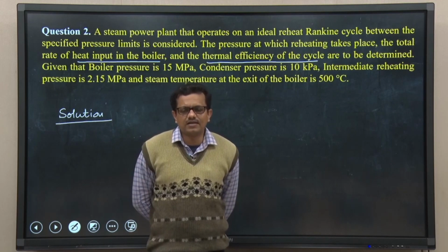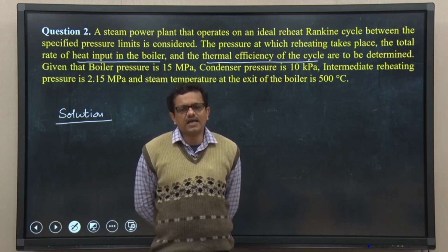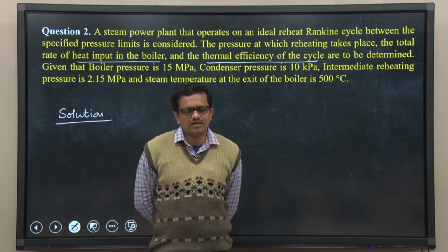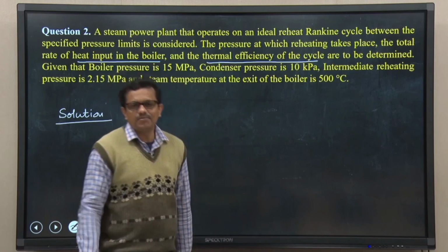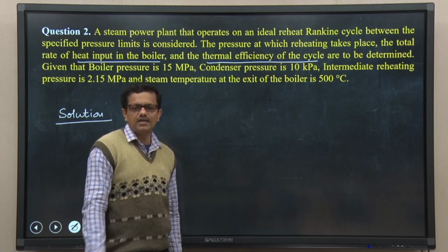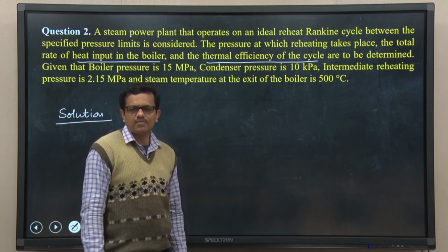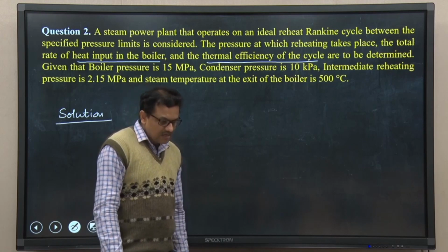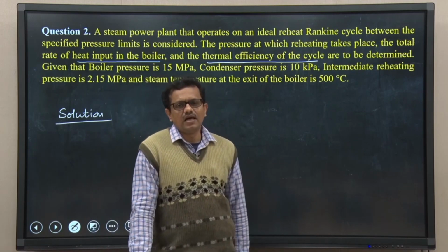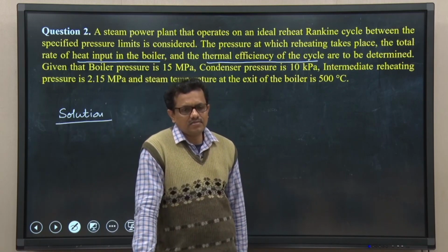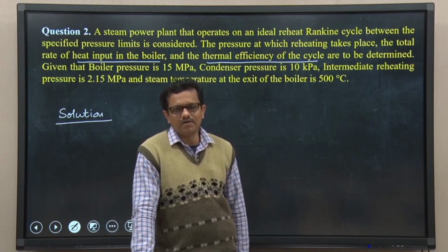If a turbine blade material is available which can withstand such high temperature without inviting any operational issue like generation of thermal cracks, then superheating steam could be an ideal way of increasing the thermal efficiency of a steam power plant.